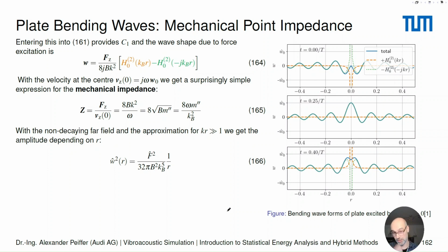In the lecture, you can also use some kind of radiation stiffness of the edges of a half infinite plate, but this is hard to explain in a lecture. And I would really recommend that you take a look at the book to get into the details of line junctions and so on. But for point-like things like here, the point impedance is very helpful and helps to understand how plate and other systems can be coupled.